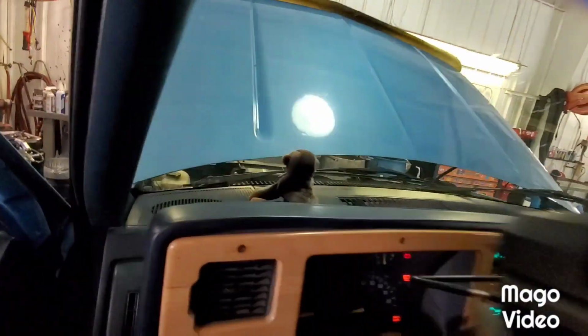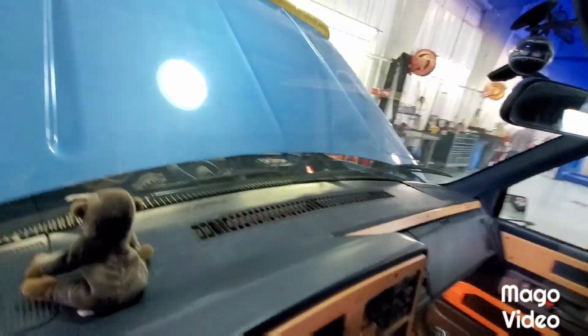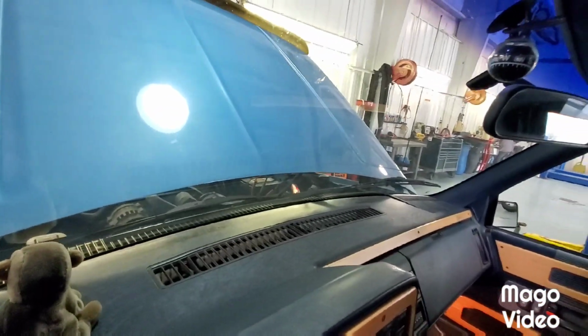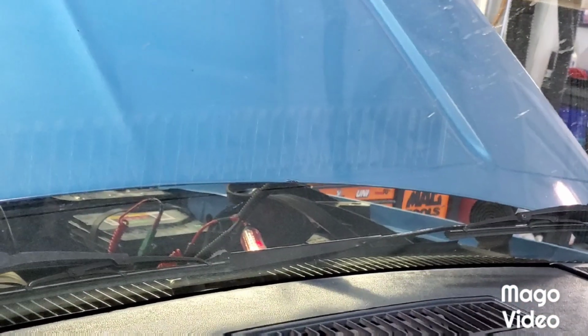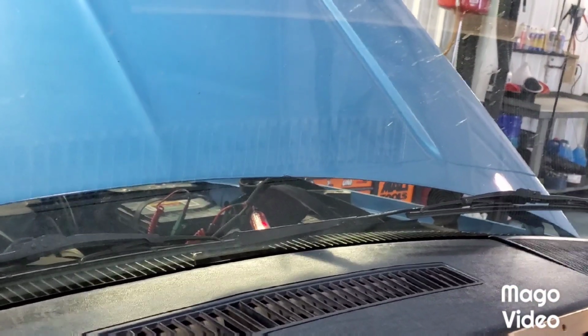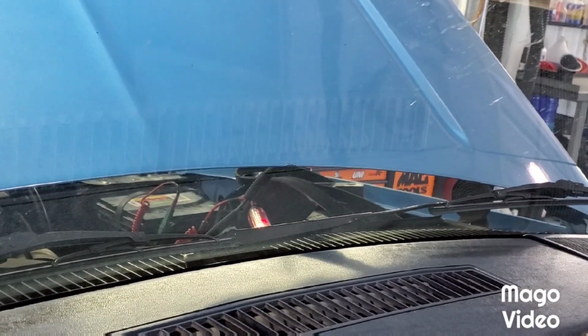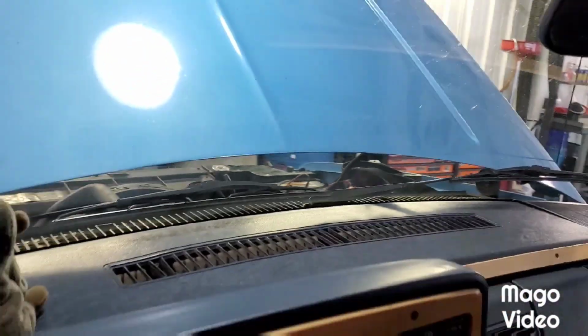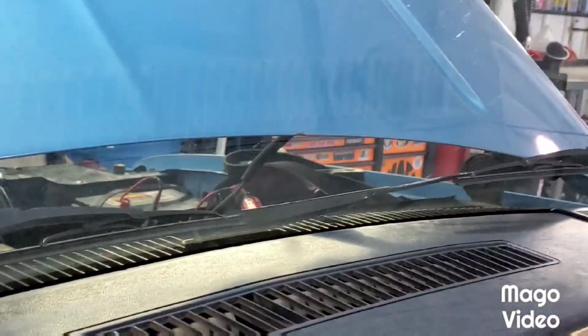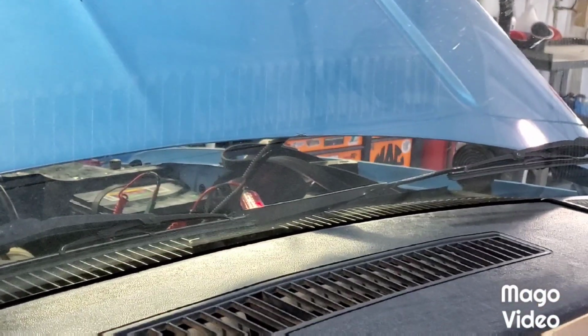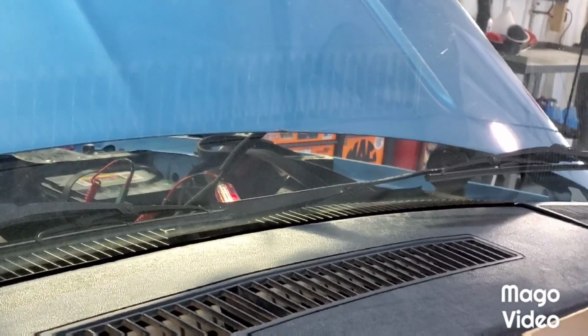All right, so I got the new relay in and I'm back probed in on the, I don't know if you're going to be able to see my test light right there. Zoom in. I'm back probed in on the gray wire, okay? And I'm hooked to B positive, so it's grounded right now. Now when I turn the key to on, it's going to prime, and that should switch over to a power.